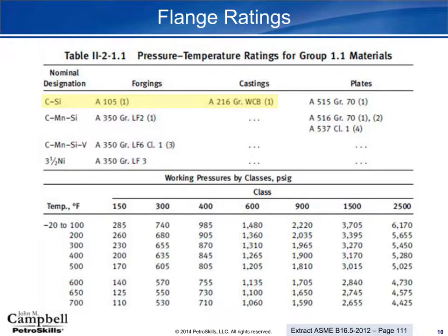And the reason that I show this is because this chart is looking up allowable stresses per class, and the allowable pressure on that flange is a function of temperature. And the reason that I want to focus on this is because if you remember our piping system, the piping allowable stress started to derate above 400. Here in our flange system, the flange starts to derate above 100.